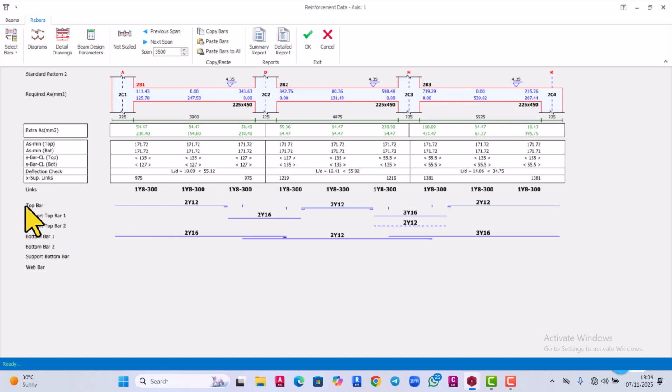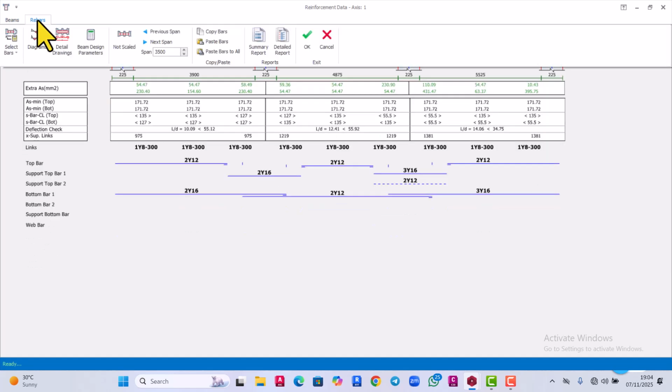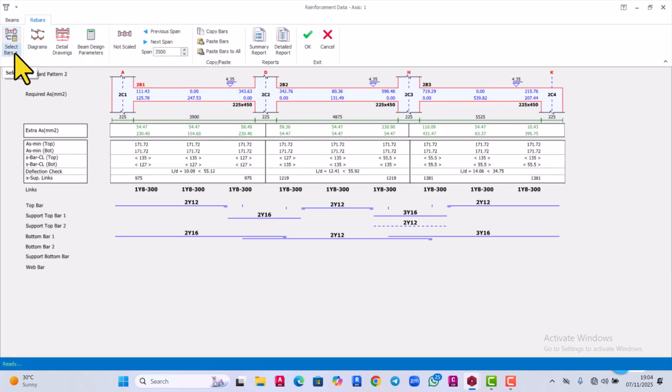Now, when you come here, this is under rebar. Now in this rebar, you can find we have different patterns. What I mean by pattern is the way you arrange your reinforcement in a beam. When you come to the Indians, mostly that I know, and other parts of the world, they use what we call the bent-up pattern.